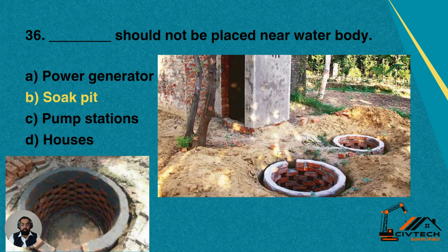First, there would be a small manhole, then the septic tank, and then at the end of the septic tank, at some 3 to 4 feet interval, there will be a soak pit. It depends on the size of the washrooms and the number of washrooms. It may be two, three, or one, but it is provided after the manhole to make the final disposal